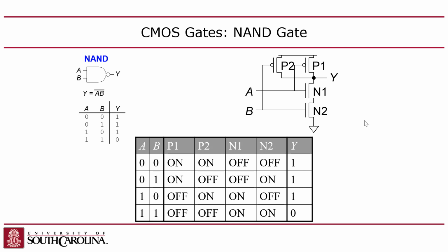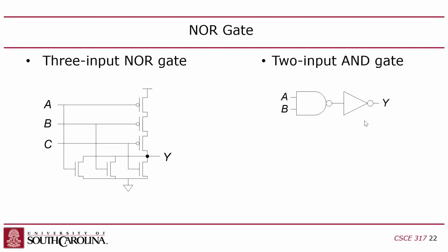I think chips nowadays run at 800 millivolts to a volt power supply. And so because we're very close to the threshold voltage, the leakage current is worse in modern chips than it was in previous generations. It's more of a concern. But it's still the most power efficient technology available.